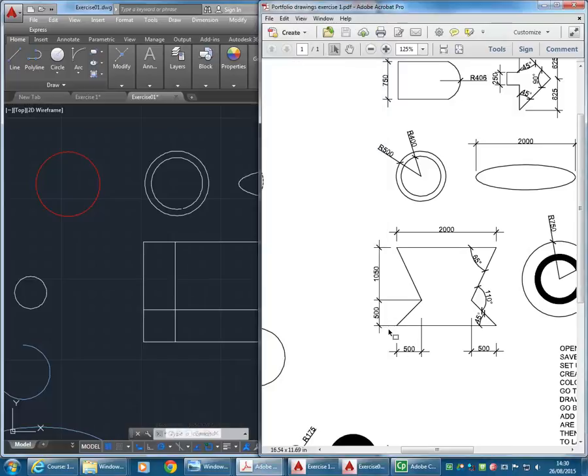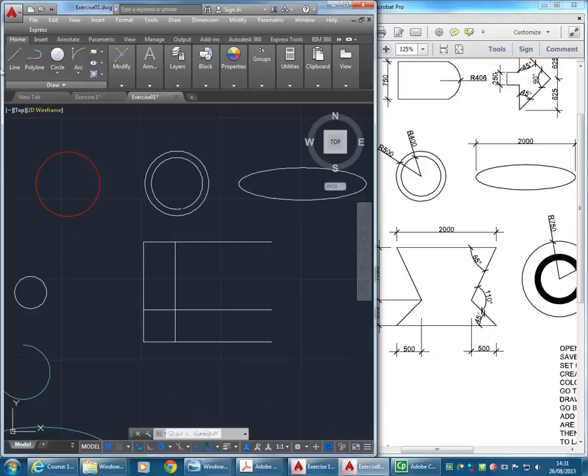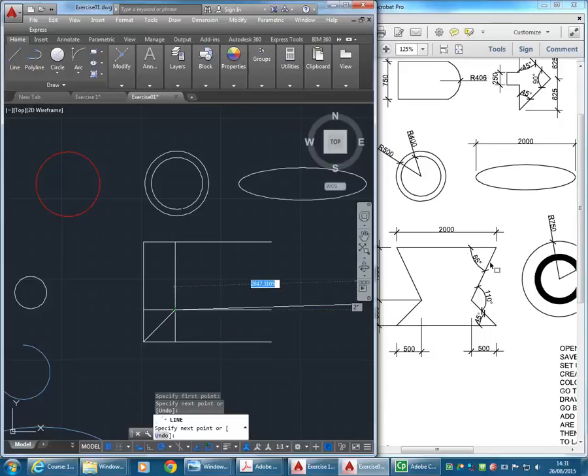Because just think about your basic trigonometry. If you come across a certain distance and then up the same distance, the angle between those 2 points is going to be always 45 degrees. Okay, so that's what I've got here. It's a square, come across 500 and then up 500, and so the angle across that square, again, is always 45. So with a line there, from the corner at the bottom, up to this intersection, will give me the angle 45. And now again, to get this angle, which is 65, same on the other side, I can just come up to the top left corner.